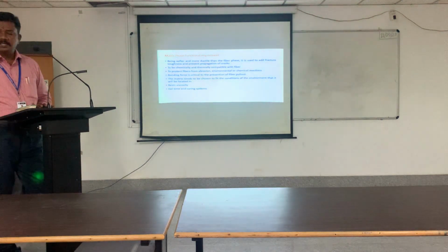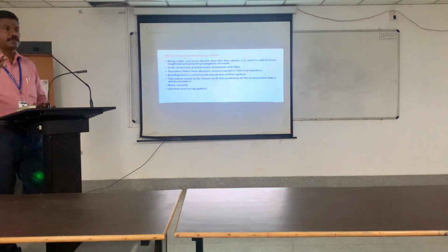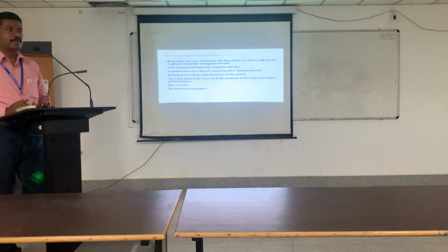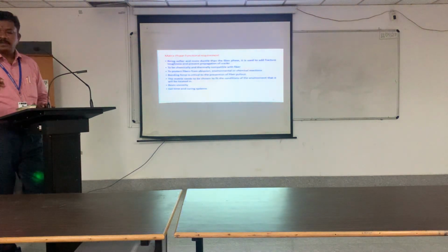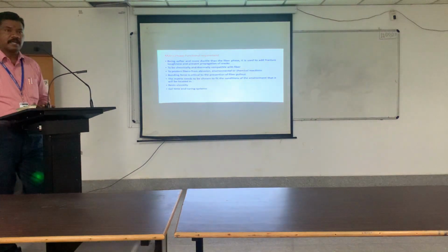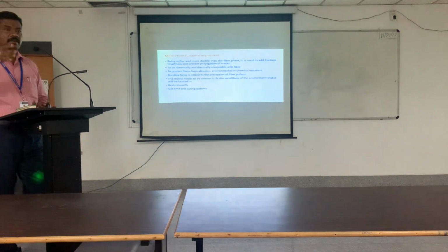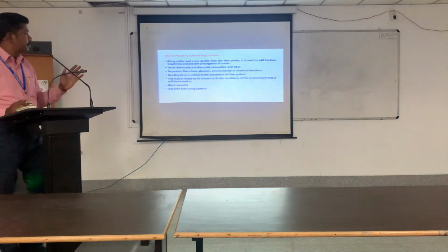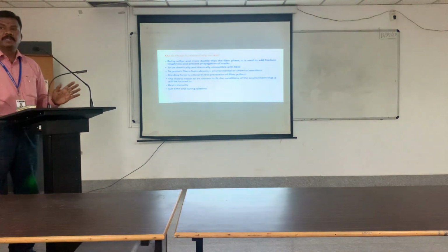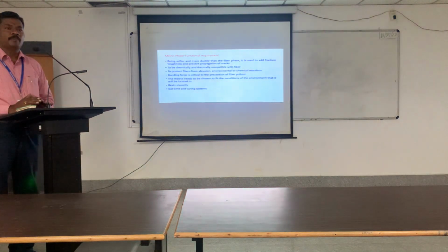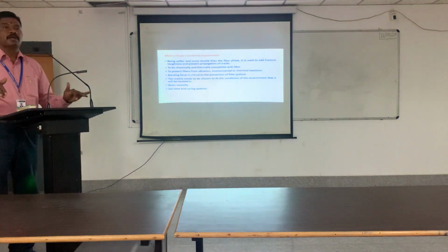If in the mild steel sheets any hole is there, that will not spread out. If any crack is there, that will not propagate very fast. But if you have a glass plate, if a small crack is there, upon application the crack will easily extend, or it will easily propagate. So in such a way, since the matrix material is softer, that will help to reduce the crack propagation.